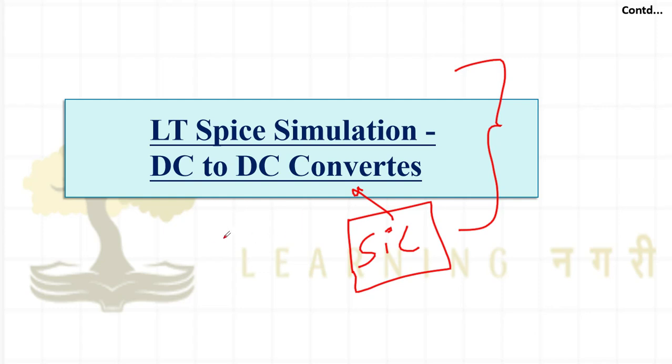Again, one more thing is how we have generated the PWM and all, right? And that gate signal we have given, but we cannot give the gate signal directly to our devices. We need to have one gate driver. What a gate driver is and all, I will tell you in later videos. Maybe you know it, that is a good thing. The gate driver provides the signal with protection.